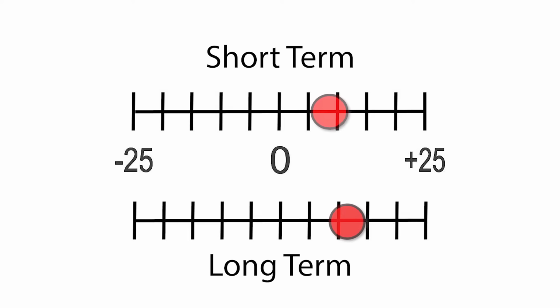And as time goes on here, you can see this chart keeps on moving, and our short-term gets real close to 0 again, and our long-term is up to positive 20. So a short-term of 0 plus a long-term of 20 equals the same positive 20 of fuel trim correction. Keep this in mind as we take a look at a real vehicle here.